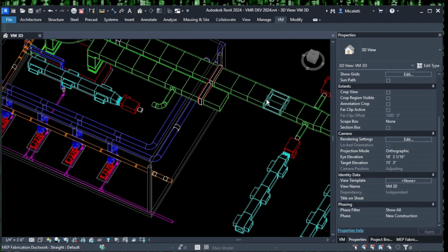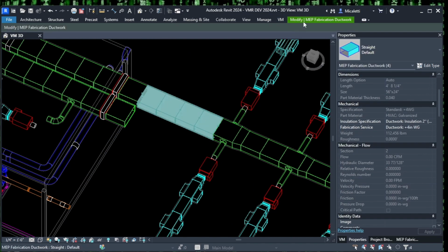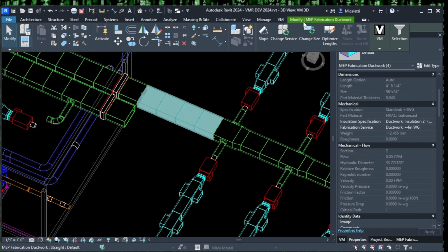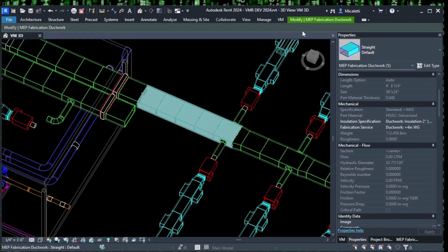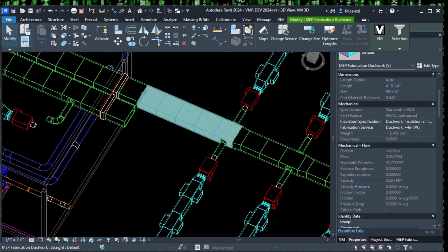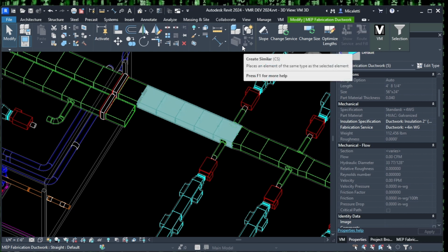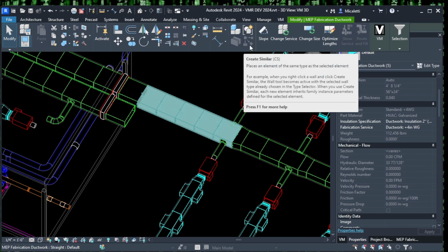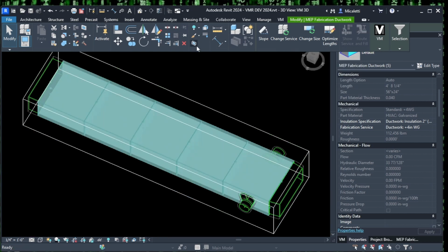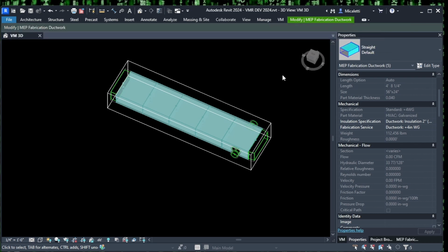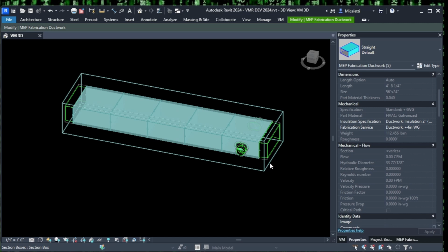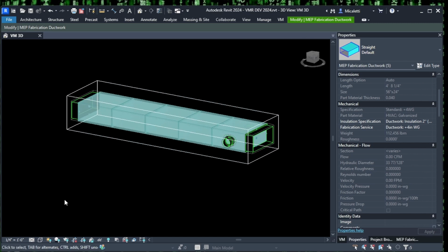Another thing you can do if you're just in a plan view is this tool. And this is really handy because you want to get in on that toilet or that bathroom. So you just select that toilet or that bathroom, right? And then you come up here. And what is it? This one? No. This one. This is going to give you a 3D view without having to make one, right? And so this tool is really good. Just go around in your 2D view, grab stuff out, then you get a 3D view and you can sleeve that real quick, right?